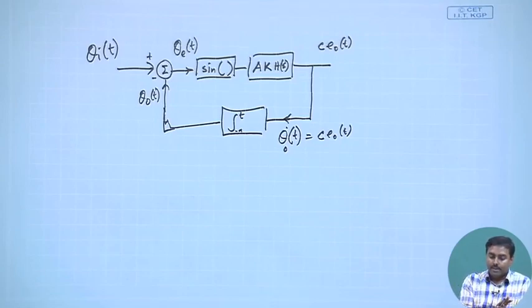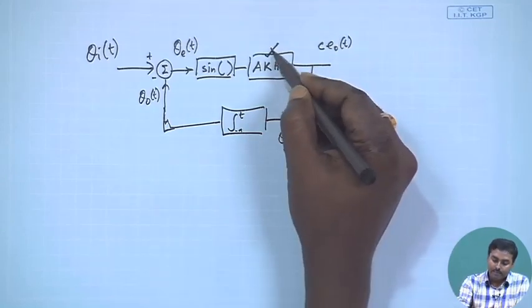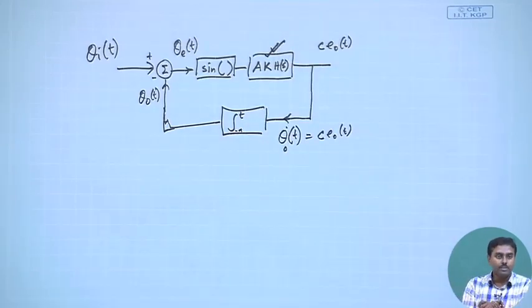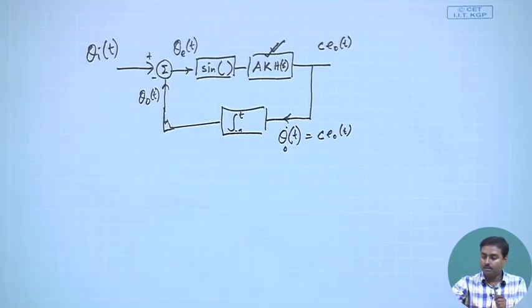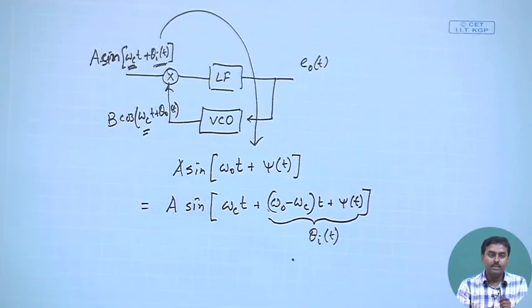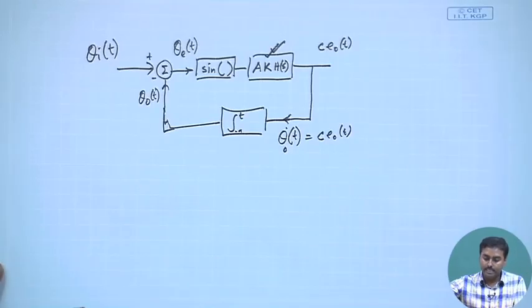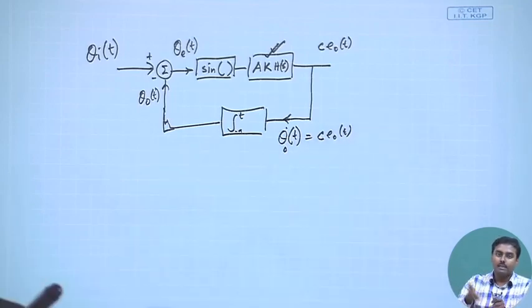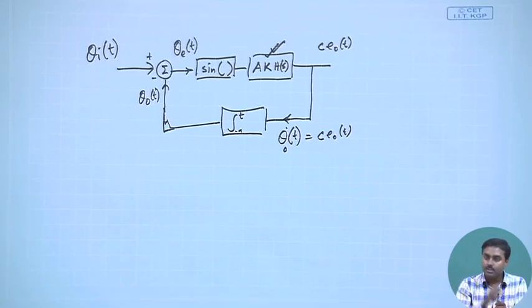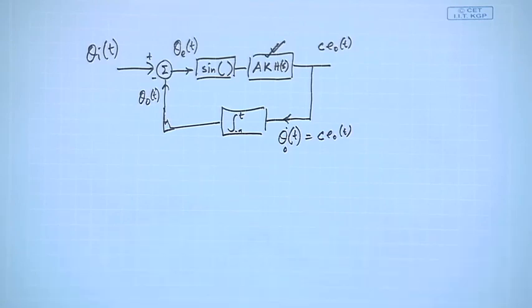Okay. So, for that, as you can see, this k parameter was typical to the VCO. It was having a parameter b, which, if you just see over here, is the strength of the VCO output signal. So, that is typical to the VCO, and then it was also having a parameter called c, which is also part of that linear variation of the frequency it generates with respect to the VCO input voltage. So, this is also a parameter typical to the VCO, and k is actually half b into c, we have proven that.